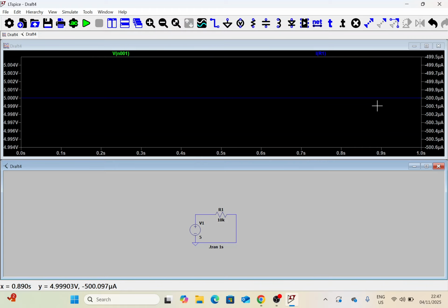microamps. And this is something I want to draw your attention to, that LTSpice for some reason has particular orientations that a component should be in for it to read current and voltages correctly. So if the component isn't properly oriented as is expected, then it will show you negative current, not necessarily because current is indeed negative, but just because of the component orientation. Okay, so just note that once and for all.